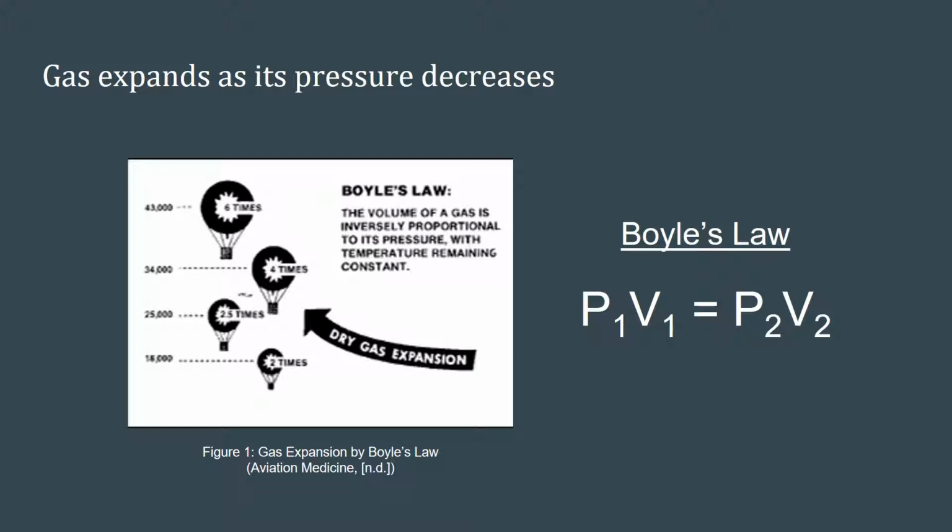So as the gas column is circulated and migrates towards the surface, the height of the column of mud above it decreases. The decrease in the mud above the gas results in a decrease in hydrostatic pressure on the gas. This decrease in hydrostatic pressure allows the gas to expand. This relationship is described simplistically using Boyle's law.